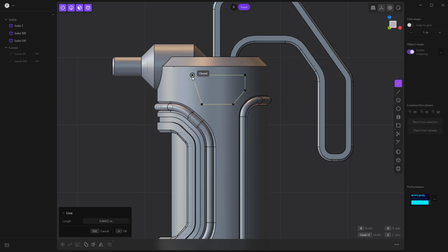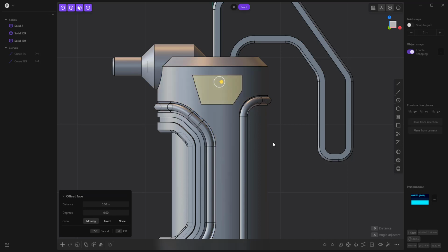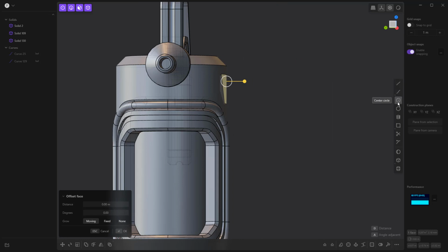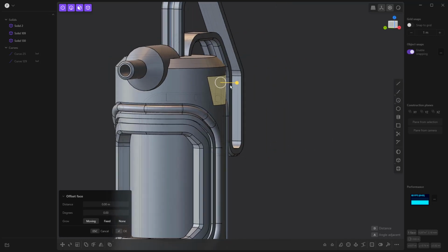Now, if we want this snap point, we can get it here, but notice that it says it's on Y. Now, if it's on Y, that means we're not on the face, and that's a problem. So we do need to be careful here. When we're using the knife tool with a curve, the curve can be a line, it can be a spline, a circle, whatever. Now we've actually taken that and divided the face up directly.